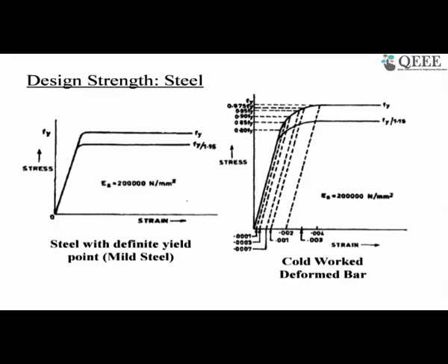For concrete, because the uncertainty in concrete is more, the partial safety factor is more. Uncertainty in steel is less because it is manufactured in a very controlled environment, that's why the partial safety factor for steel is less. Okay, now the concept of partial safety factor we don't have as it is in other design philosophy. In reinforced concrete structure, we have only two materials, concrete and steel, that's why the safety factors for material strength are discussed only for these two materials.